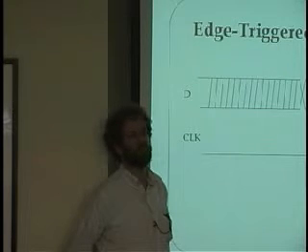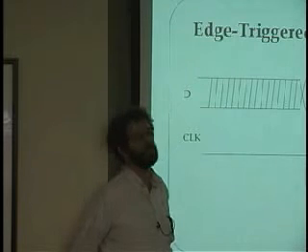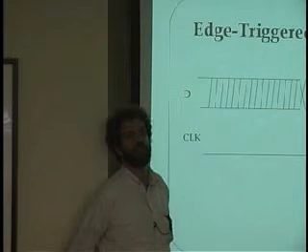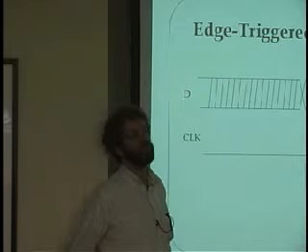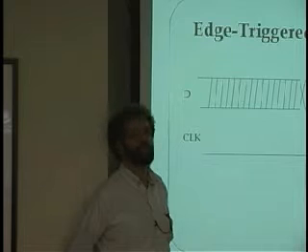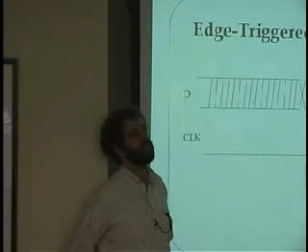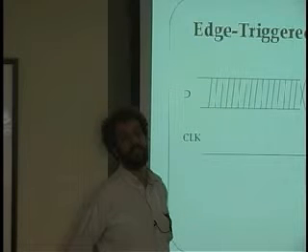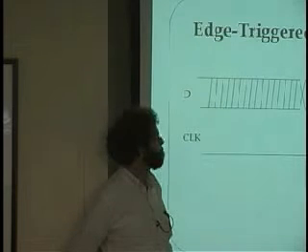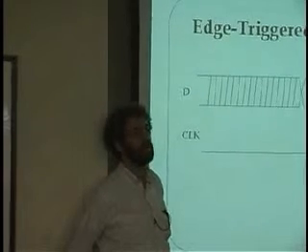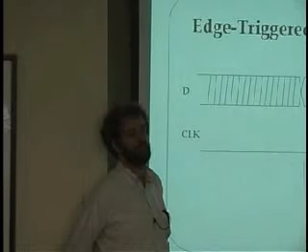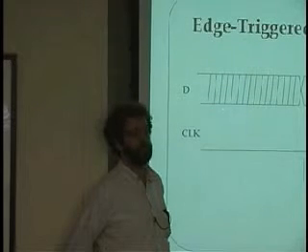And it's given over the entire range of temperatures and data values. Okay, so for any data value and any temperature within range from minus 20 degrees C to plus 100 degrees C or something like that. And it turns out that there are different specs depending on whether you build parts for the military or for the home. These are always given in terms of worst case. Okay? And the clocks are adjusted accordingly. And when you design the system, you decide how to clock it exactly by that.